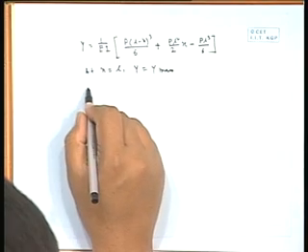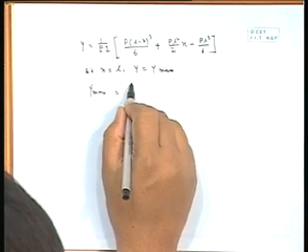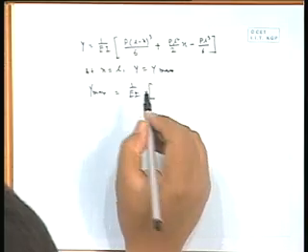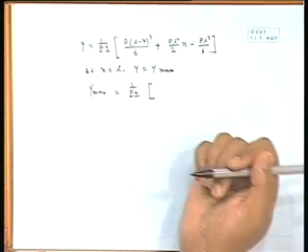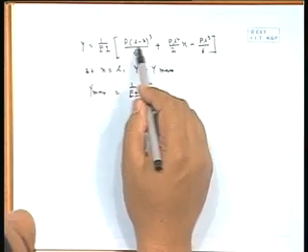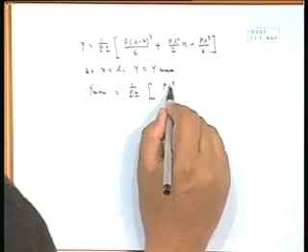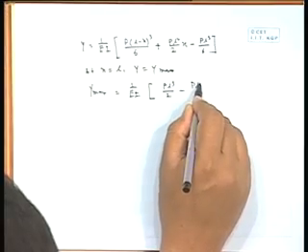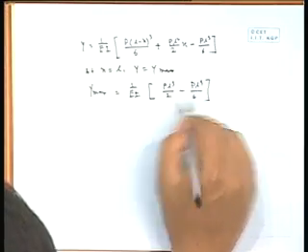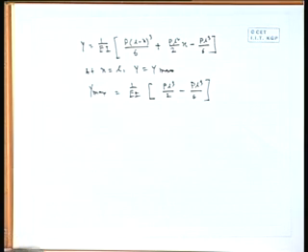But if we are interested in finding out the maximum value of y, so at x equal to L, y equal to y max. So, y max will be 1 by EI. The first term will be equal to 0, because x will be L, L minus L, it will be 0. So, there it will be P L cube divided by 2 minus P L cube divided by 6. So, basically both are P L cube.